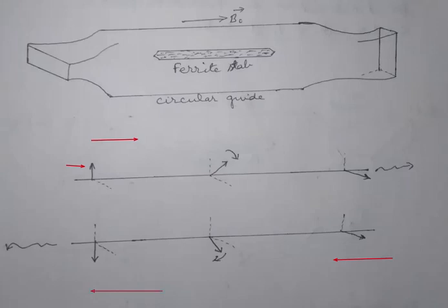In this way we can explain the construction of a gyrator in two designs, one with a 90 degree twist section and the other without any twist section. The gyrator can be used in microwave benches in which a relative phase difference of 180 degrees is required. We will use this device in the construction of a 4-port circulator. Thank you.